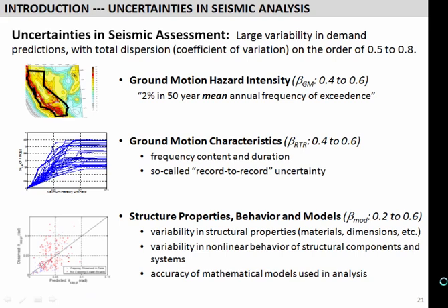But also recognize there is structural modeling uncertainty, that is in the parameters we build into our analysis. So while we're starting with a median model, and in general a lot of our criteria are then going to be acceptance criteria about the mean demands on drifts or the mean plus a standard deviation or some factor of that, recognize that's all from a mean model, that unless you start to vary the modeling parameters, you're not even capturing, if you will, that so-called modeling uncertainty.